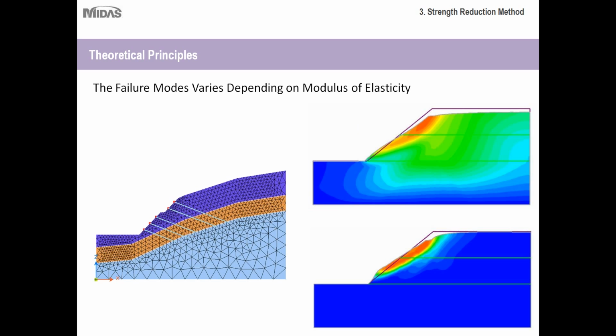So it's really important that you have your modulus of elasticity magnitude in there correctly, and that you have it lined up with the right material. Otherwise, you could get erroneously high or erroneously low deformations.